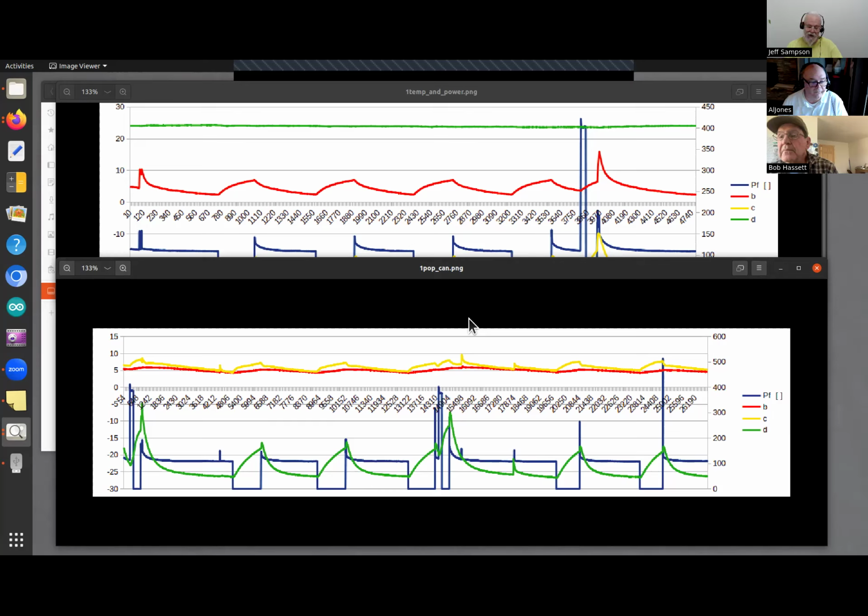If you cut it down to 11 bits, it drops by half to about 375 milliseconds. At 10 bits, it drops again to 187 milliseconds. At 9 bits, it gets down to about 87 milliseconds. So by adjusting the resolution, you can control how long it takes to run.